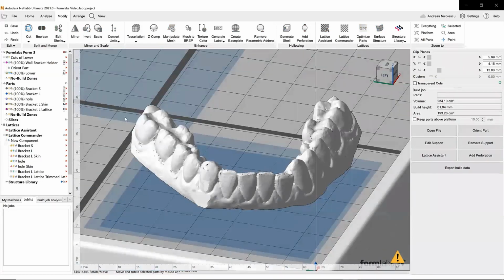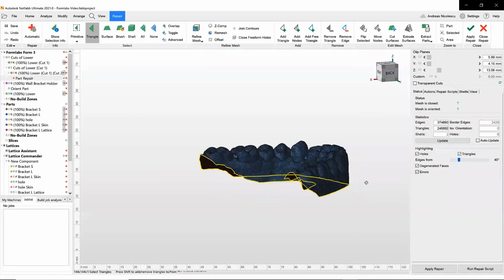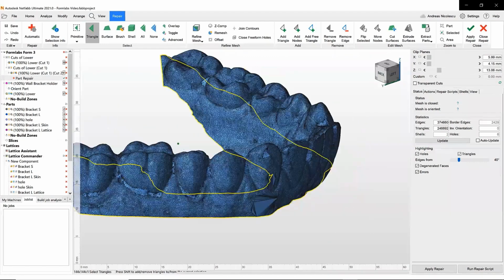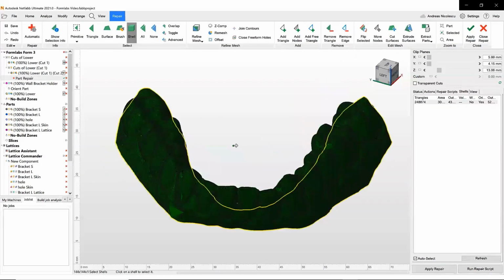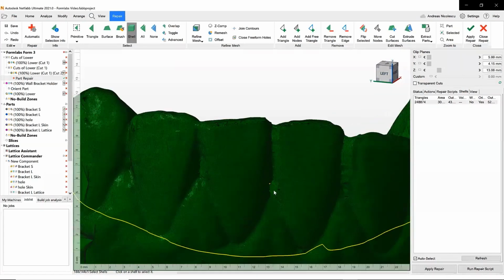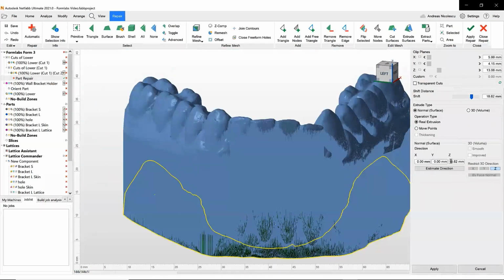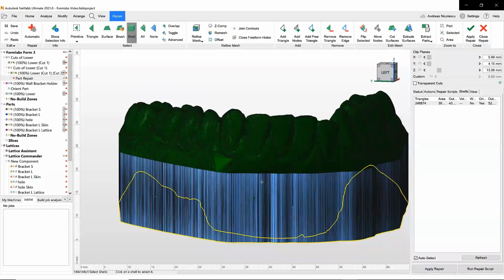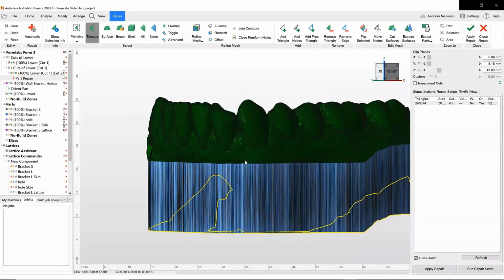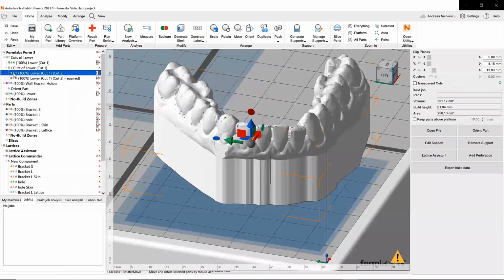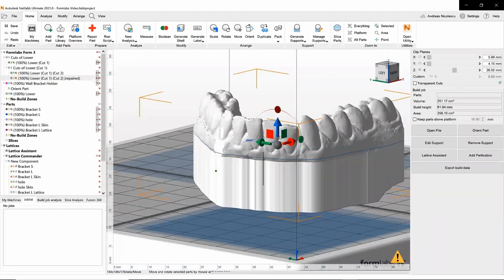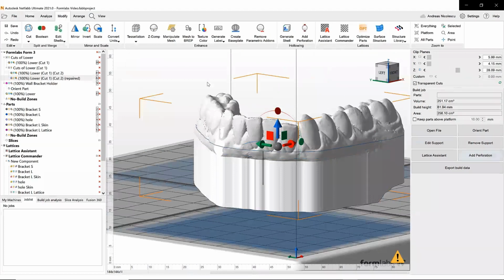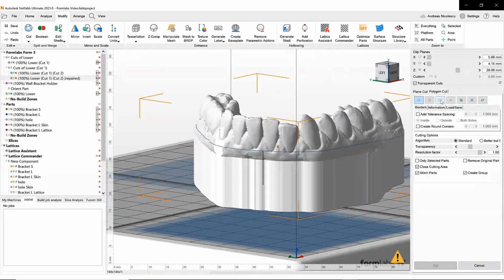In the repair module, we can now see how the big yellow edge is defining the open contour of our part. First, we are going to remove all noise shells that may be a side product of our cutting activities so far. The main part here in this module is the extrusion in Z direction so that we can get a good enough base for our solid model. After the extrusion, we have enough material that we can work with to create a solid. We can use a plane to cut and stitch the parts and by that finish our fixing process.